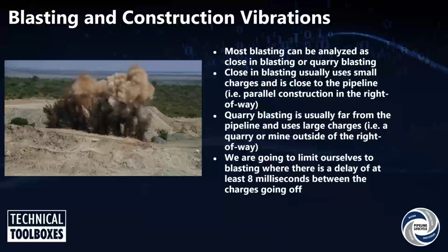So, blasting and construction vibration. There are two general methods to assess the effect of blasting on a buried pipeline. And again, today we are only going to talk about the buried pipeline. If the pipeline is not buried, there are other concerns when dealing with blasting, such as trajectories hitting the pipeline.